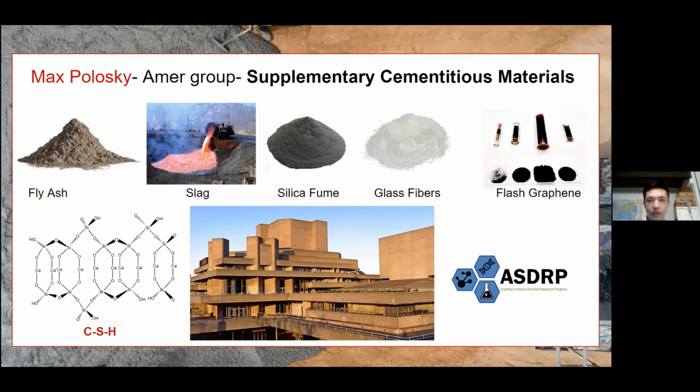Third, I'll define cementitious. So cementitious describes any materials that react similarly to cement, creating a strong compound called CSH, as you can see there, which is integral to concrete strength, but also creating a byproduct called CH, which is weaker, which is where the next term, pozzolanic, comes in.